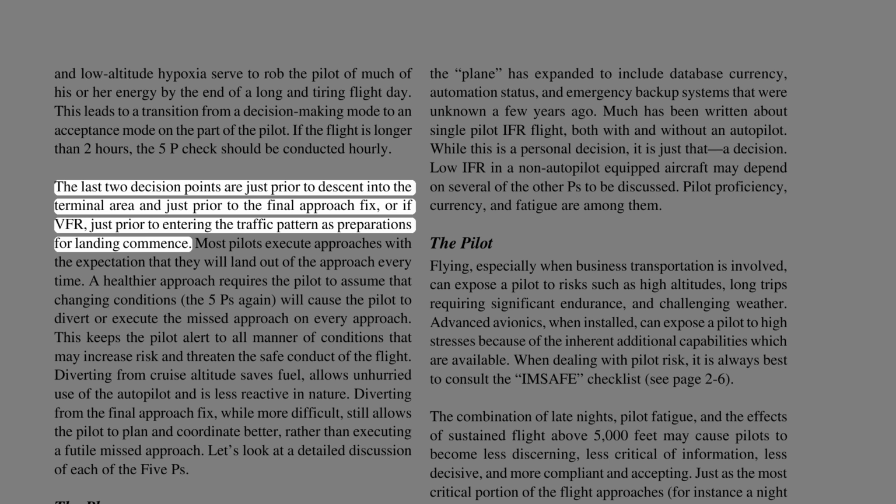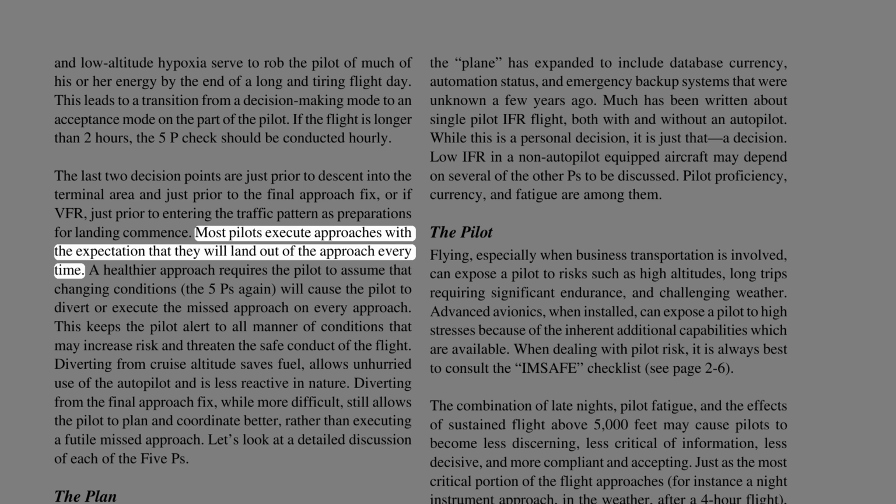The last 2 decision points are just prior to descent into the terminal area, and just prior to the final approach fix, or if VFR, just prior to entering the traffic pattern as preparations for landing commence. Most pilots execute approaches with the expectation that they will land out of the approach every time.